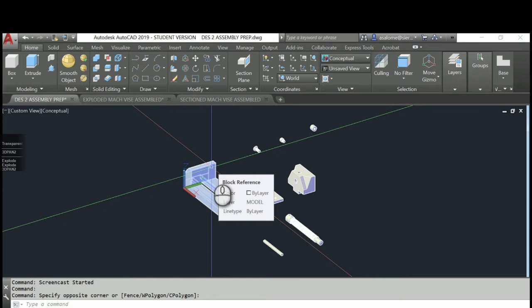When we do a W block and send that part out the way that we did to extract it from the other drawing, it creates its own file, and in that file, it is a 3D solid. But when we insert it into another file, as we've done for each of these parts, it gets defined as what's called a block reference.